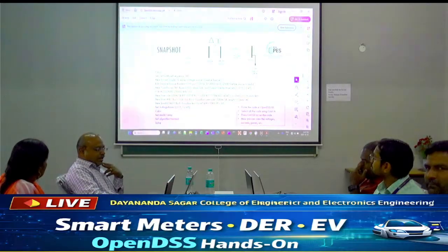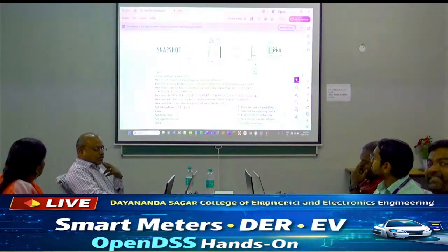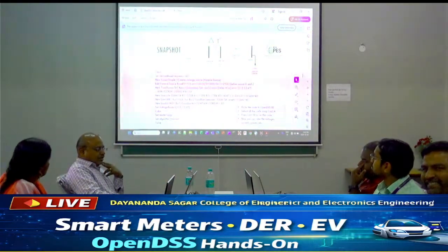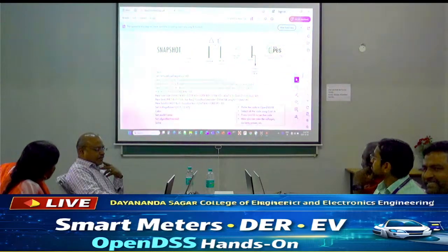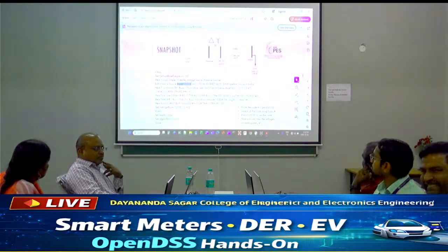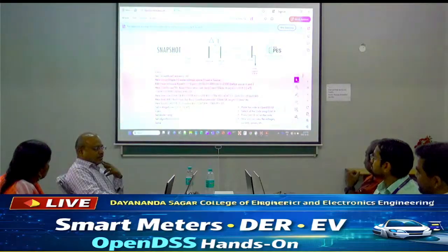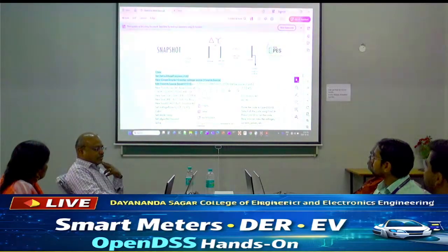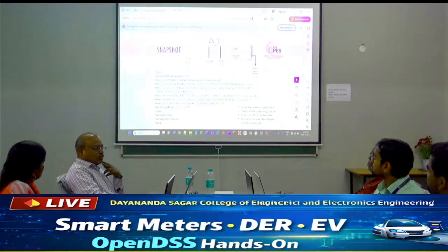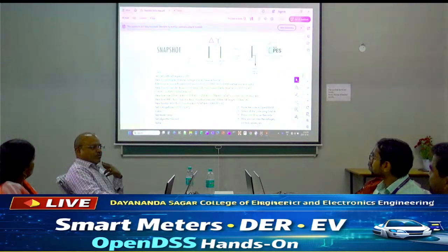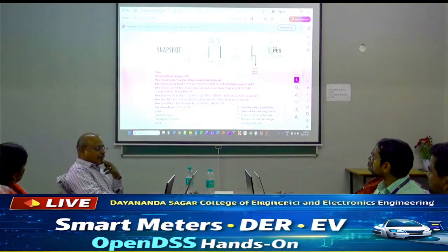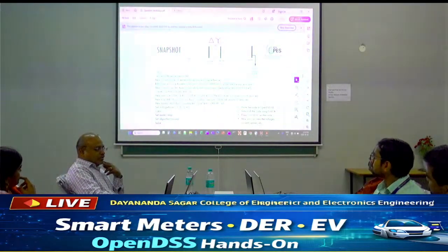And then it will by default create the voltage source for the circuit. Then we define the voltage source, where we give the base kV and the per unit value to start with, P 1.05, so automatically the voltage will be 1.05 times 115 kV. Then you have the short circuit current, everything you define for this voltage source. And then you define this transformer.